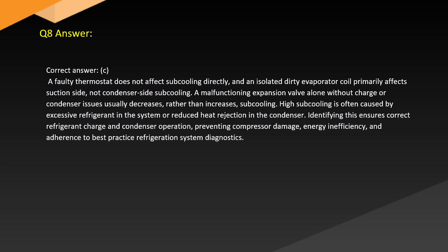Answer. Correct answer: A. A faulty thermostat does not affect subcooling directly, and an isolated dirty evaporator coil primarily affects the suction side, not condenser side subcooling. A malfunctioning expansion valve alone, without charge or condenser issues, usually decreases, rather than increases, subcooling. High subcooling is often caused by excessive refrigerant in the system or reduced heat rejection in the condenser. Identifying this ensures proper refrigerant charge and condenser operation, preventing compressor damage and energy inefficiency, and adhering to best practice refrigeration system diagnostics.